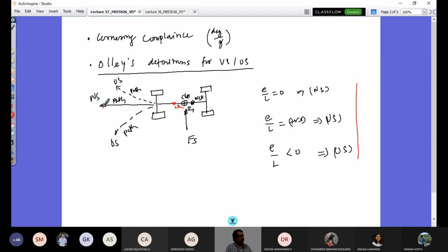Let us now look at the influence of suspension on lateral dynamic aspect. So for that, we need to understand importantly roll moment distribution. Roll moment distribution, right? So what do you mean by roll moment distribution? The roll is the motion of your vehicle with reference to your longitudinal axis, right? So as you take a turn towards right, you would have your lateral load transfer from inward to the outward side. So the roll will take against that of a turn.